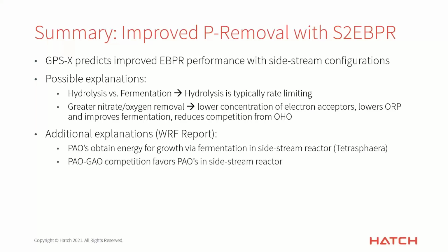Secondly, some researchers believe that at these very low ORP conditions in the side stream reactors, PAO growth is actually favored over GAO growth. But the report does stress that more research is necessary to really nail down the significance of the contributions of these mechanisms, because it's still up in the air exactly what's going on in the side stream reactor. So we're currently evaluating the contributions of these mechanisms from a modeling point of view,